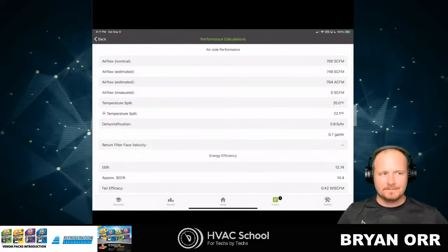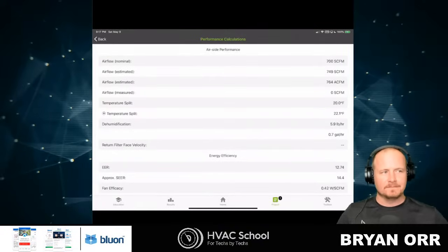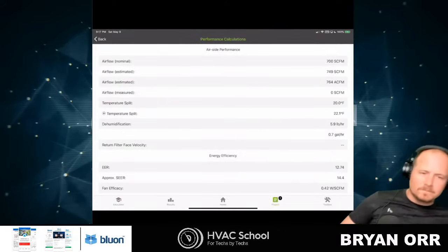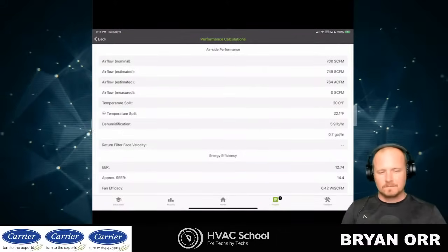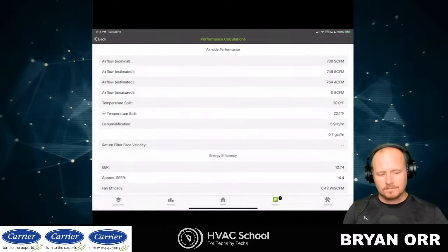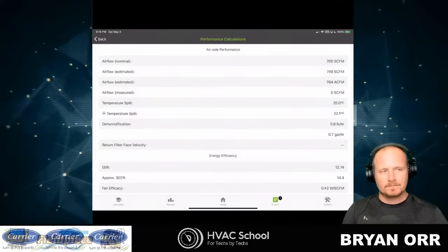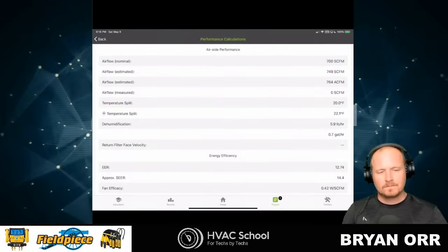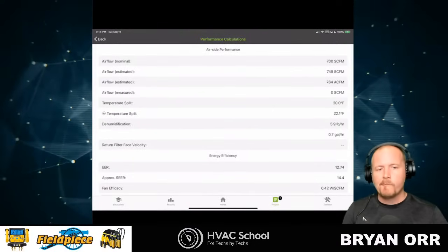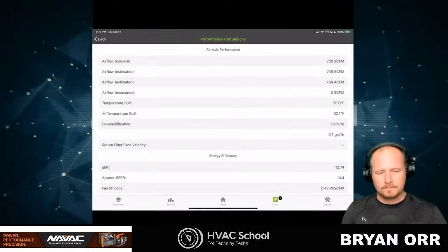Yeah, it's because you've got pressure drop through the condenser coil. If you look at a Carrier system, a lot of times on the package rooftops, they actually have a discharge pressure port, and you'll notice that they run about 17 degrees of subcooling. If you took a standard unit and measured the subcooling at the liquid line, if there was a pressure port there, you'd find it's running about 10 degrees of subcooling. So that's accounting for the pressure drop of the condenser coil.